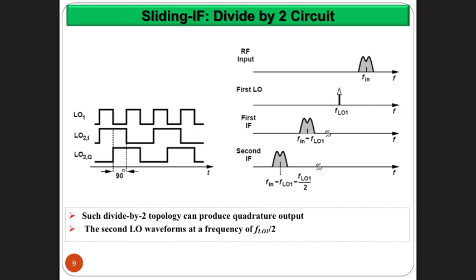Now, can we use the same local oscillator with no multipliers or divisions and then do what with it, to bring it back to zero? How do you do that? Because if we multiply by a certain frequency, we can consider that as subtracting that frequency. Maybe if you can divide it into two parts, so it takes it 50% of the way to zero, and then the other 50% is done, so that eliminates the... That's one way, yeah, but that's a special case of the general solution.